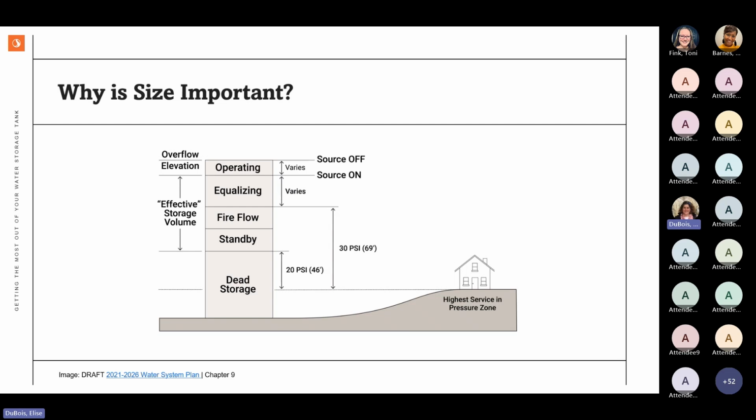When you're homogeneous, you're treating the same water quality, meaning your residuals are the same. Everything is very much the same. It's great. We love to see homogeneous tanks. So when we model the mixers, we look at all of that and try to get the best mixing volumes that we can, so you have more active mixing than less. We do know that it doesn't change a lot after 2 to 3 hours in your tank, but over the course of several days, typically about 3, the water does move all the way through the tank.